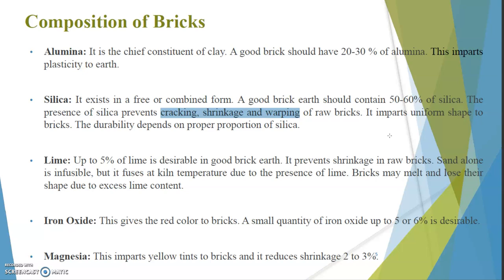Once cracks develop severely during drying itself, and you subject the same cracked dried bricks to the burning chamber, it will not give you a proper output. So automatically your output will be of deficient quality.